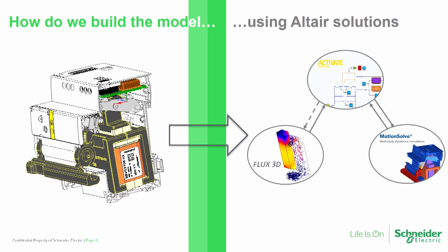Co-simulation exists, we've tested it, but in most of our applications, except if you want to take into account very complex phenomena, such as eddy currents or hysteresis material, response surfaces are good enough, and it's much faster in computation time than adding a 3D finite element model into the loop. And the big difference is that we replace the 1D Modelica component by a MotionSolve model.